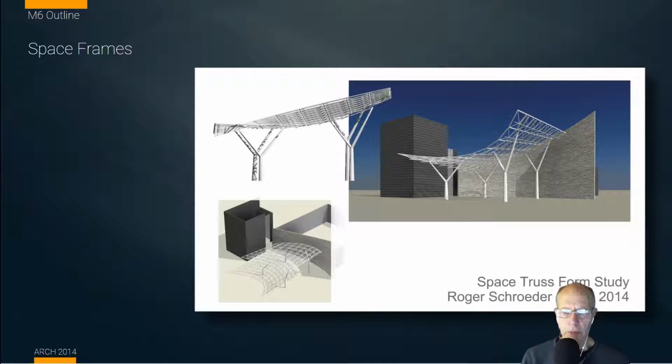We're then going to keep it elevated and supported by these adaptive columns that we're going to create. And the magic of this whole system is that once we've created all of these elements in the structure, we can go back and modify our shape to make it more aesthetically pleasing or interesting, or whatever we might decide to do aesthetically. And our components will adaptively conform to the new surface that we create.